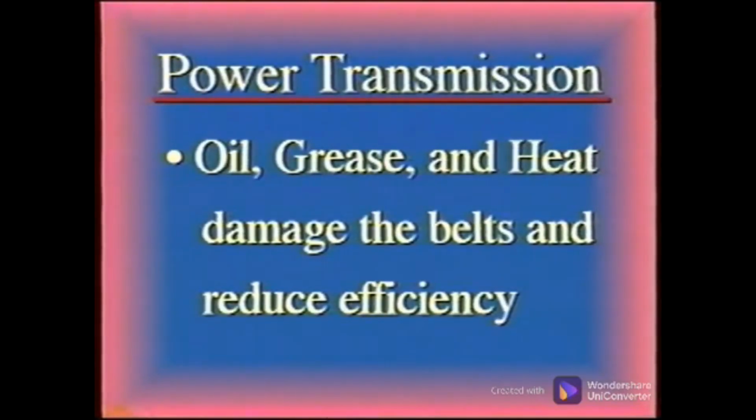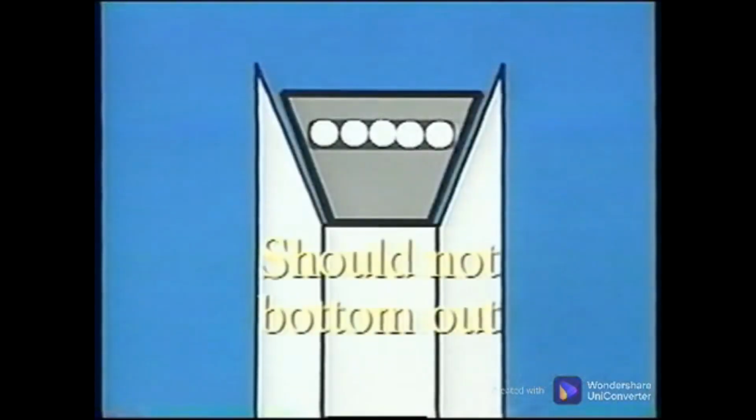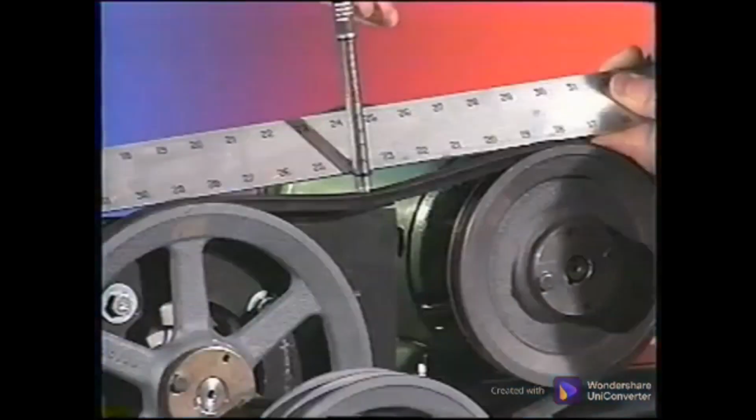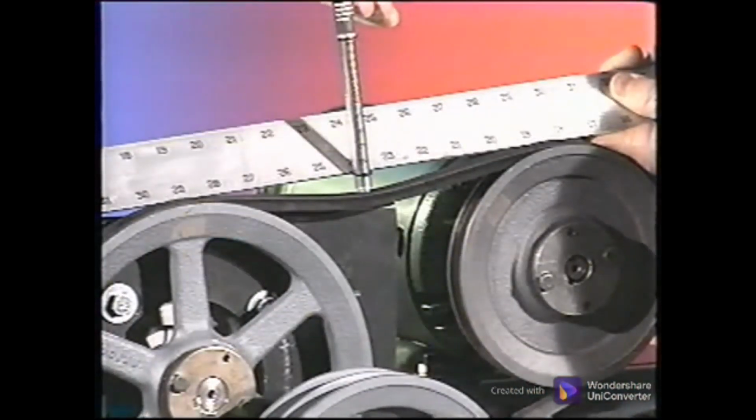The presence of oil, grease, and heat damage belts and are the most common sources of efficiency losses. The friction is affected by belt tension, which must be enough to force the belt into the groove and hold it tightly against the groove walls. The belt must not bottom out in the sheave, because the sheave then pushes the belt out and away from the groove walls. The proper belt tension is the least tension that will keep the belts from slipping. More tension accelerates the wear on the belts and sheaves and puts extra load on the bearings, shortening their life.